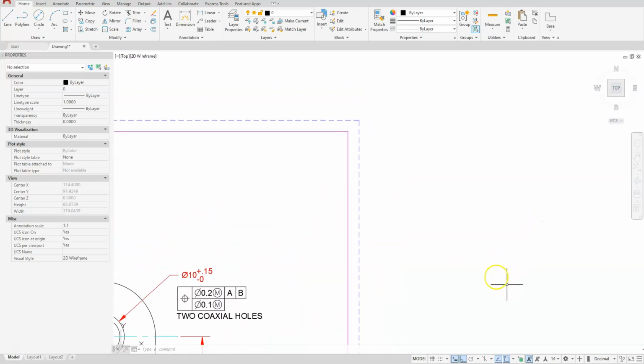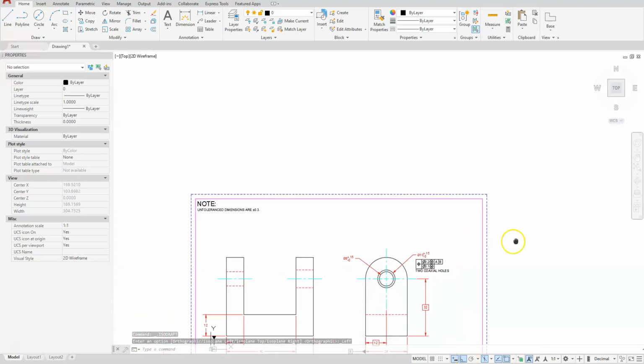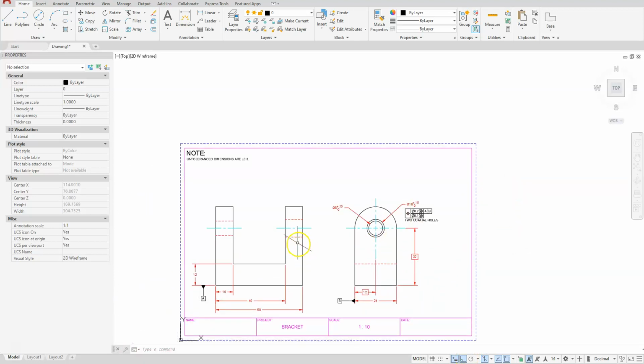Okay, so if you're going to do isometric drawings, remember we have to set AutoCAD up in an isometric. I'm going to click this icon. Make sure that you have your ortho on when you're creating these. Now you can either choose to get the dimensions from over here by measuring, and that's simply just doing a linear dimension from this end point to maybe this end point, and you can see that that's 20.